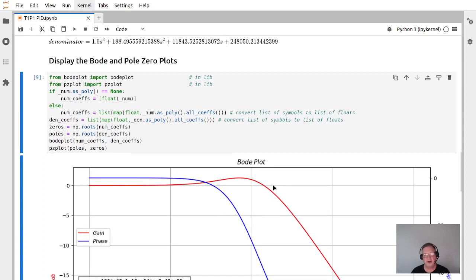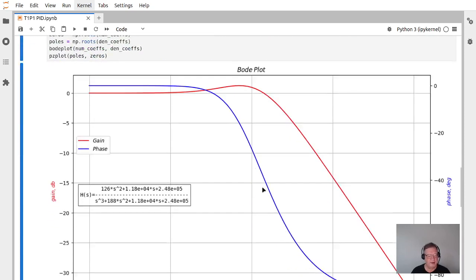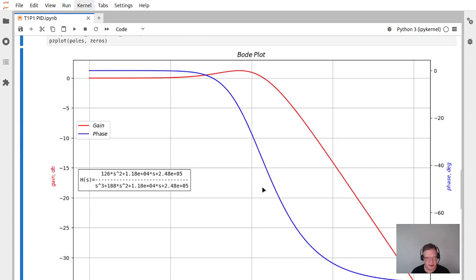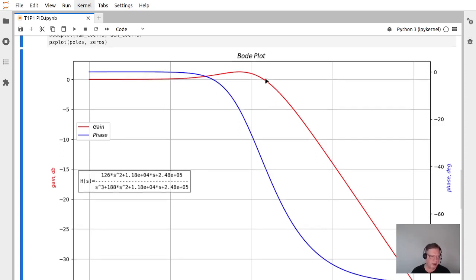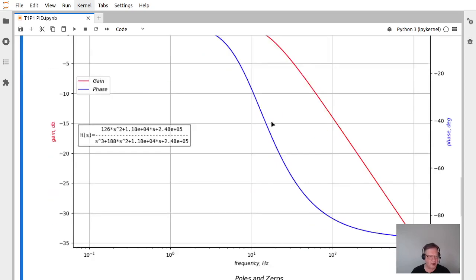So the zeros extend bandwidth, but at the expense of having the possibility for overshoot. And this is why you want to use a target generator whenever you're doing motion control as opposed to doing step jumps, because I guarantee you, if you do a step change in the set point or target position, you will get an overshoot.